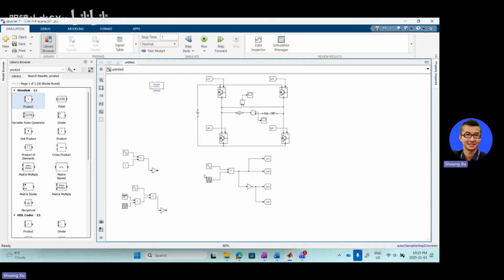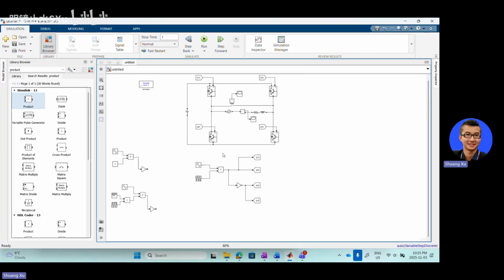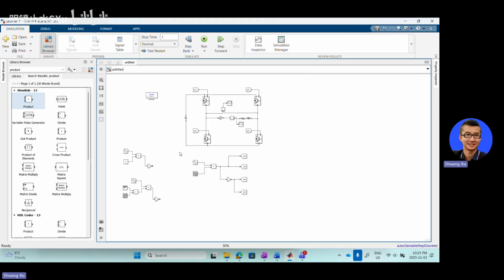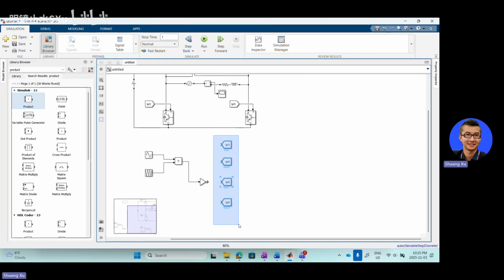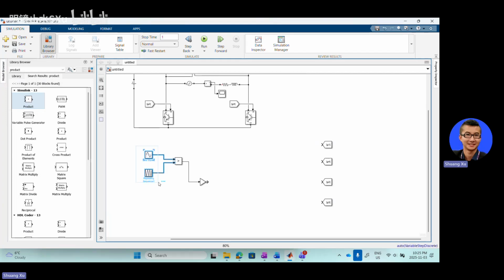Okay, we will continue to the double frequency unipolar SPWM. If we still remember, it's also similar to the bipolar. Instead of using just one reference, we need to have two references. One reference is compared with the carrier wave to control leg 1.